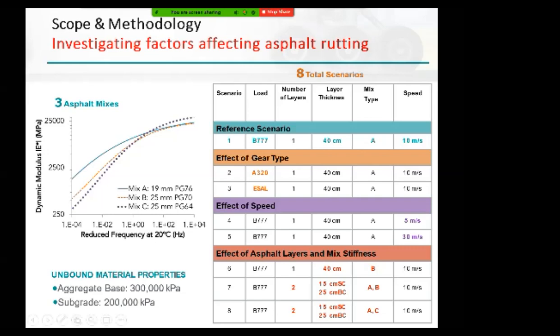So I will try to change the gears and apply the gears of an A320, and I will try to run an ESAL, specify an ESAL, and look at the viscoplastic strains, how they are going to change, keeping everything else constant. And then I wanted to study how speed affects the viscoplastic response.